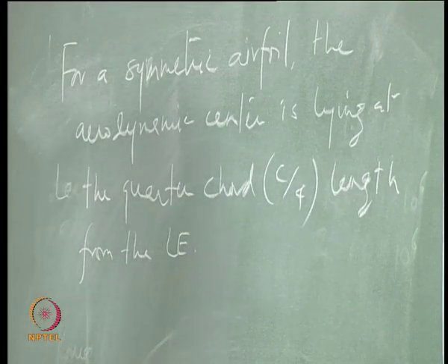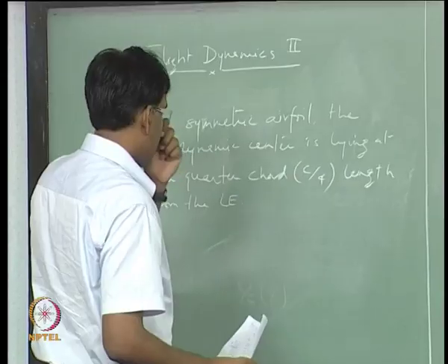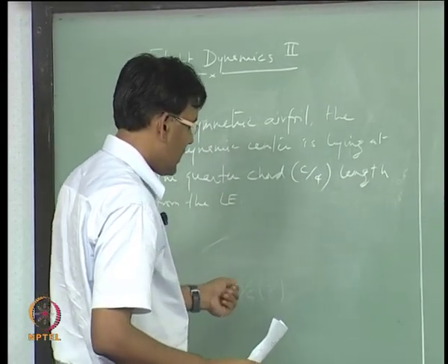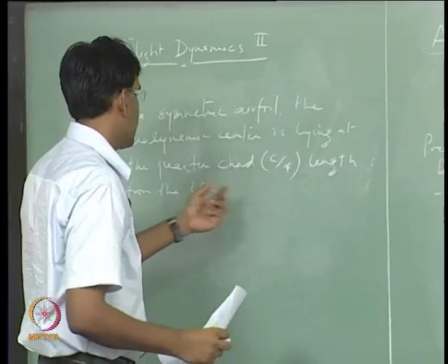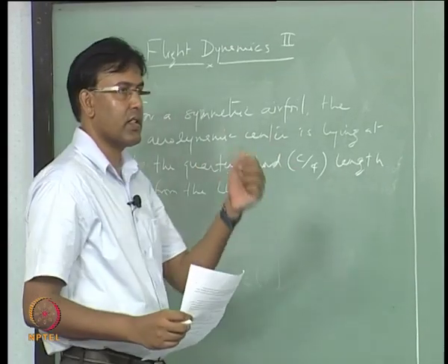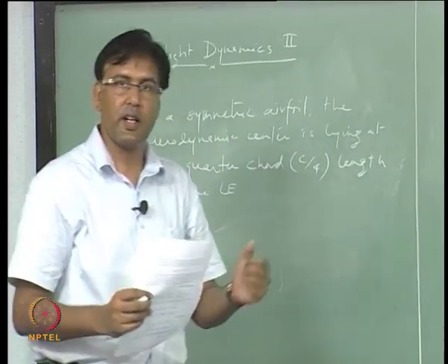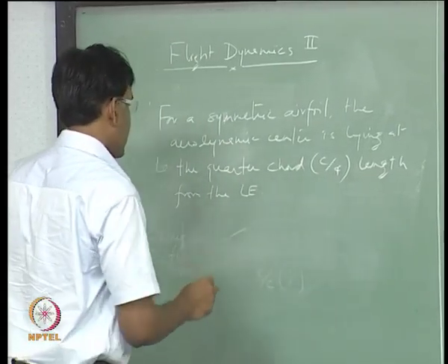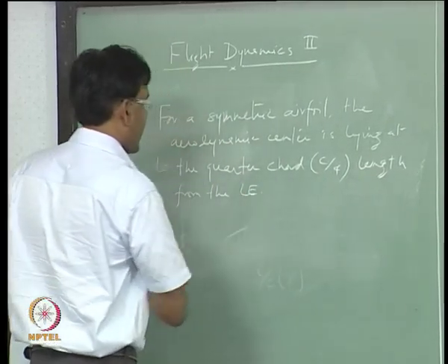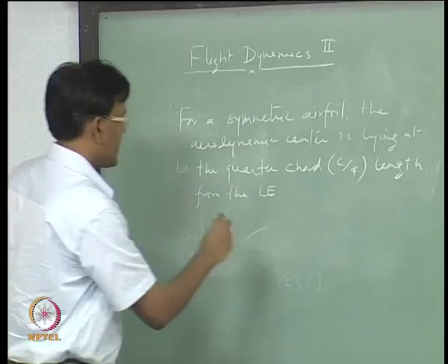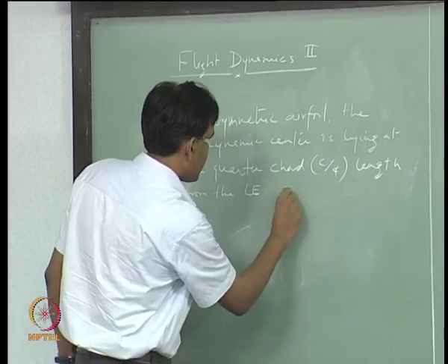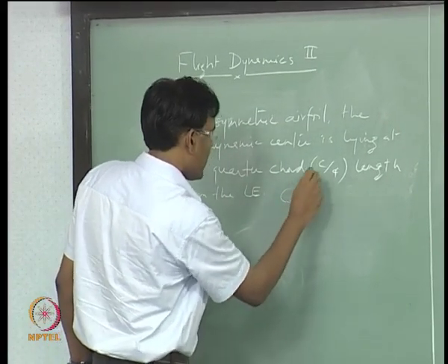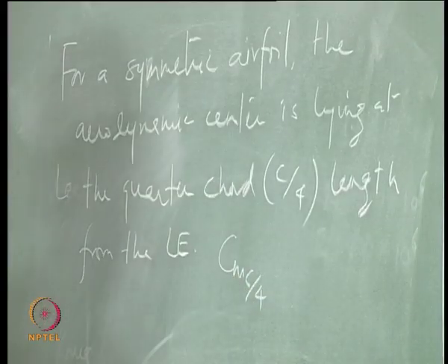So, for a symmetric airfoil, the aerodynamic center is also the point where the resultant load on the top and the bottom surface is acting, and that gives me Cm at the quarter chord.